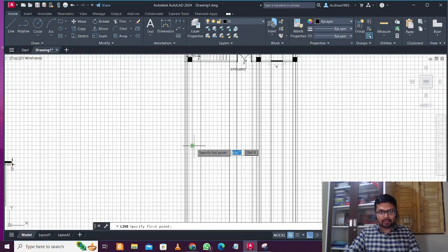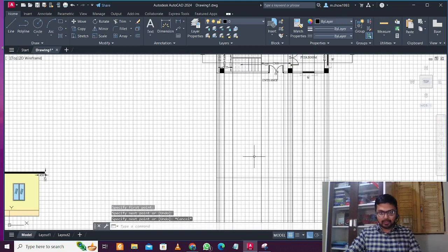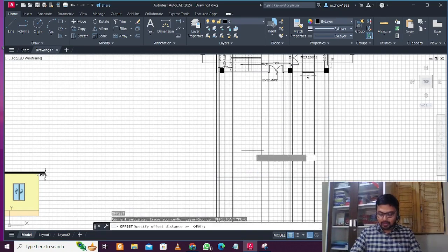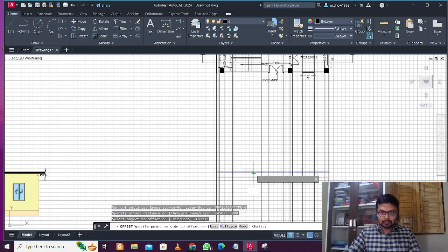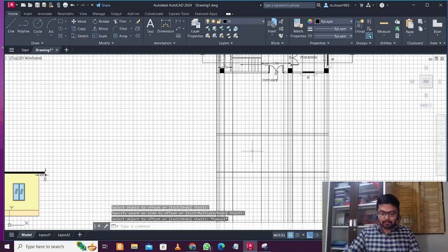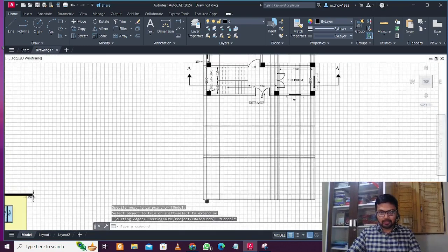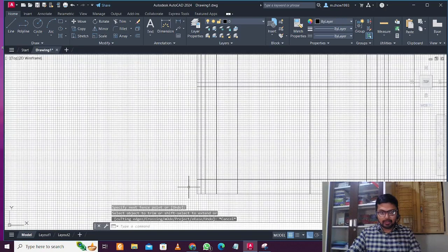We have the line here. Let's take the line representing the ground level, and plinth level 450, plinth level 3000, then 125 slab, then 2400, then 125 slab. This time we don't delete anything unless it is finalized. Yes, you can delete the bottom part to avoid confusion, but let's start with this.